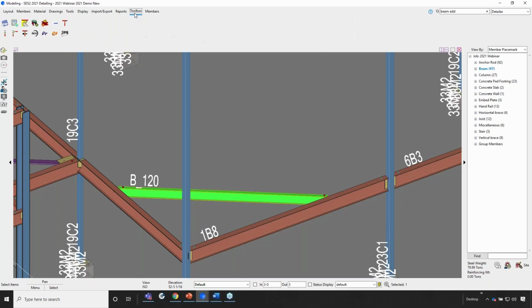But the last thing I'm going to mention here is the toolbox. So when you download certain items from our toolbox, it will give you another page here on your ribbon to allow you to do additional toolbox features, or basically run those items. So in this case, if I want to dimension members, just a simple tool to throw that dimension on there. You can see we've got some for the EMI handrail export, a Zeman export, a Strumis, AGA, the galvanizing export is on here as well.